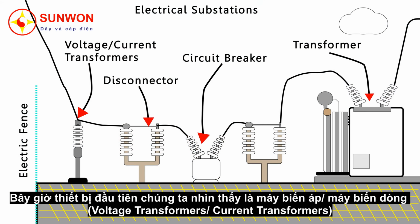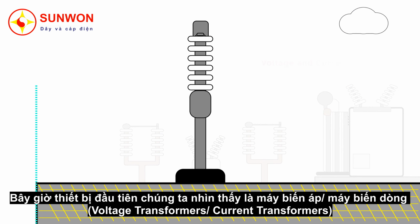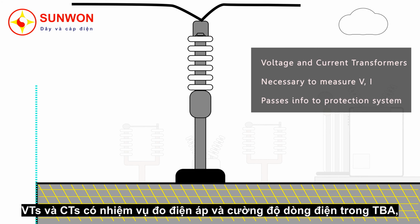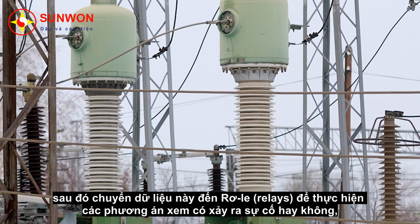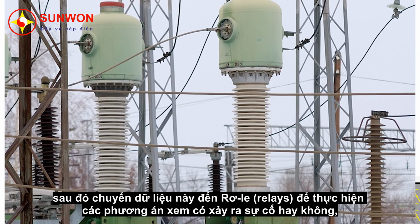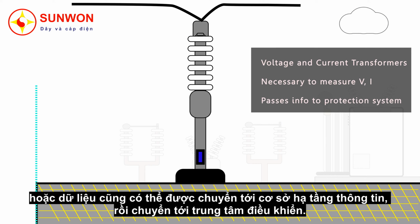Now, the first asset we'll look at is the voltage transformer or current transformer. Normally a substation has both. VTs and CTs have the job of measuring voltage and current in the substation. It then passes this information either directly to a relay to make the decision on whether a fault condition is present, or it goes into the communication infrastructure of the substation and then is passed on to the control room.